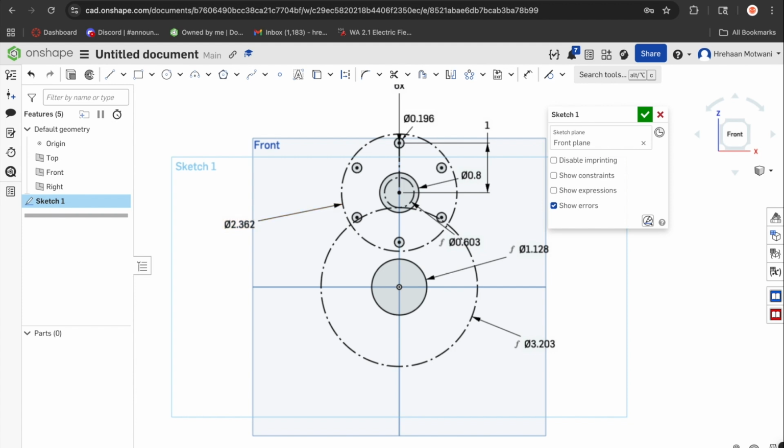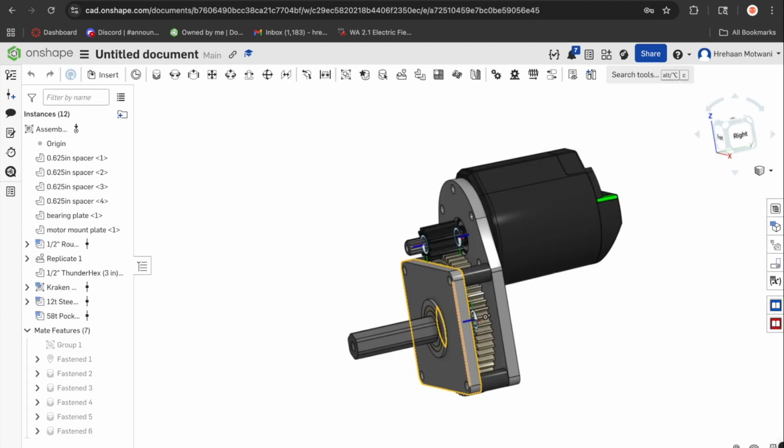And then you would do the outside of the plate. There's going to be one plate for mounting the motor, and then there's going to be the gear, and then there's going to be another plate which holds the gear in place. So you're going to need to CAD holes for the spacers that the screws are going to go through. Like on this one, you have this other plate that holds the gear in place.